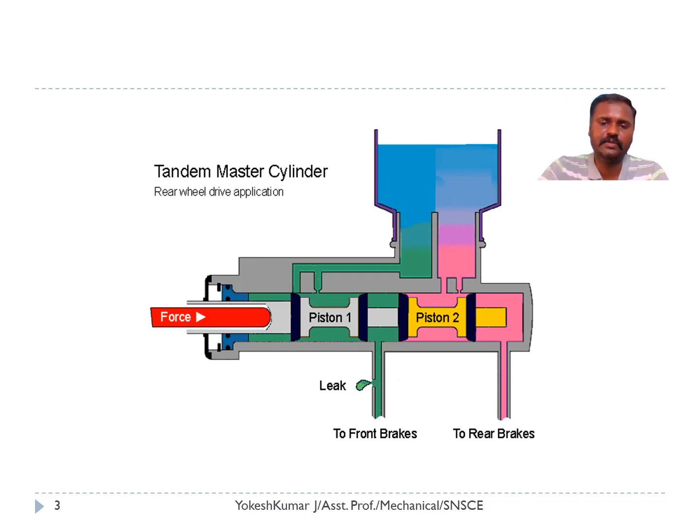Here, even if there is any small leakage, that will be compensated because we are using two pistons. So the pressurized fluid will be entering into the brakes. So this is the typical application of the tandem cylinder.